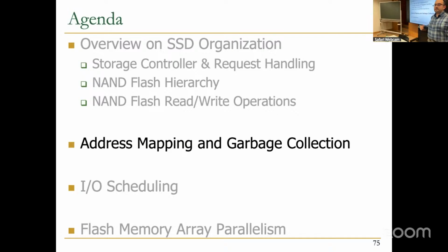Yeah, exactly. And swapping is easy with flash memory architecture, because you have this logical to physical mapping. In DRAM, for example, we don't have that easily, so remapping is not an easy thing to do. Is it because DRAM has more precious capacity, more precious cells, so you can't afford to just take some other random location and ignore that one?